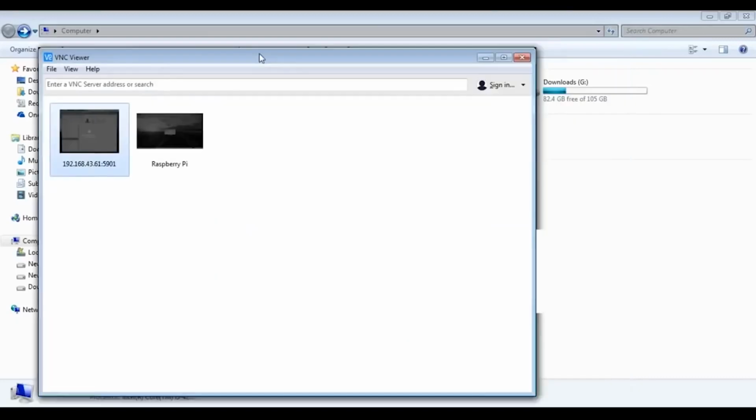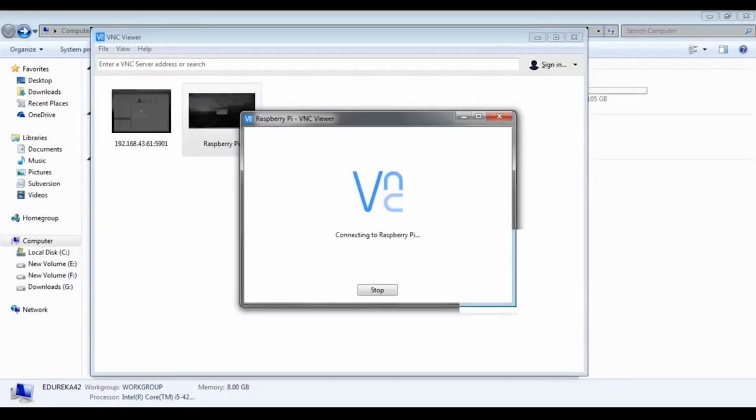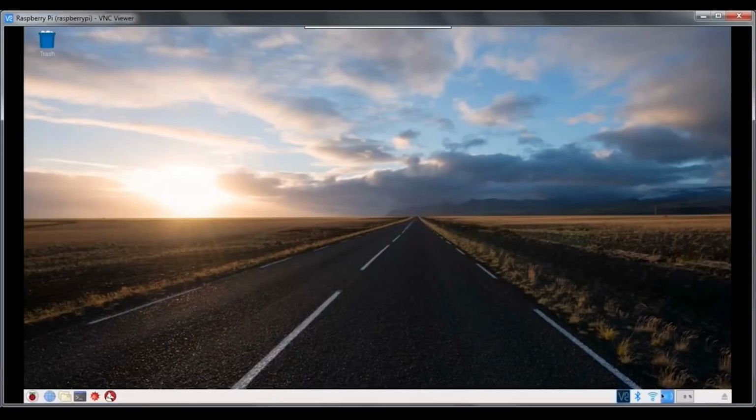Now I'm going to connect to my Raspberry Pi using VNC network. It's a virtual network which I'm connecting to because it's not quite easy for me to record the video on the Raspberry Pi. So I'm going to use VNC server for that, and I'll give you a simple idea of how you can connect the VNC server to your Raspberry Pi as well. One essential thing if you are connecting to the VNC server is that you both need to be on the same network. So I have used a hotspot and connected both my Raspberry Pi and my laptop to the same network.